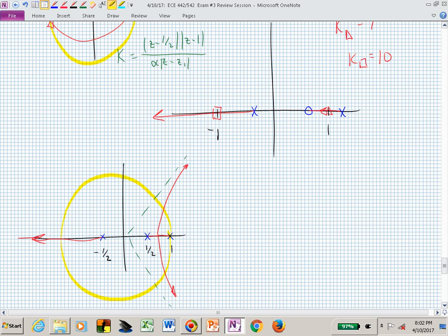You're right on the boundary. But now you would be looking at gains here and gain there, and checking to see if you have all 3 branches simultaneously in the unit circle for those locations of closed loop poles.